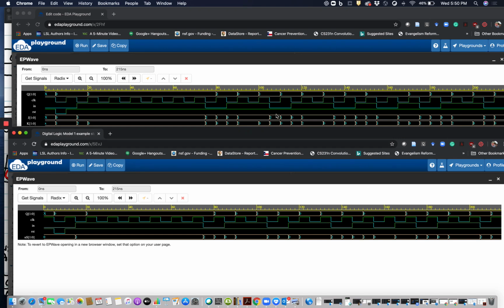That lets you see that the designs accomplish the same exact output, because all that matters is that on the same input, and you can verify they're the same input, they get the exact same output for as long as it's running. And that's what we care about, right? That we get that same functionality. So therefore, we have been able to verify that our new design is indeed working. And you can look at the values of J and K to check, but it's easy enough to see the inputs and outputs are identical, therefore we're good.